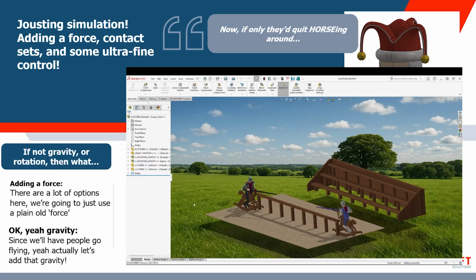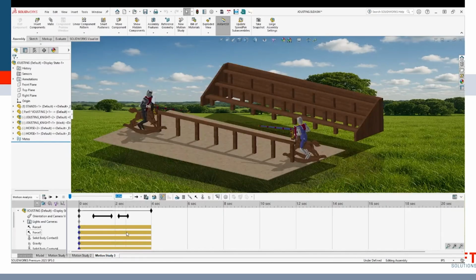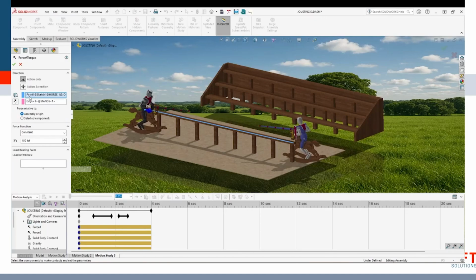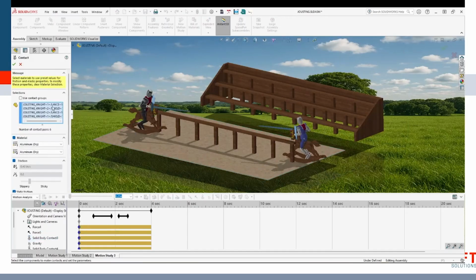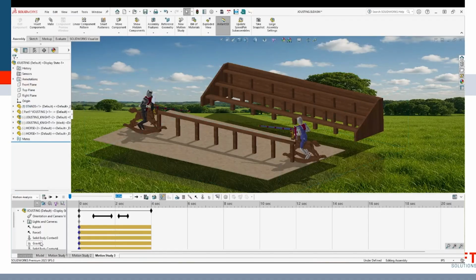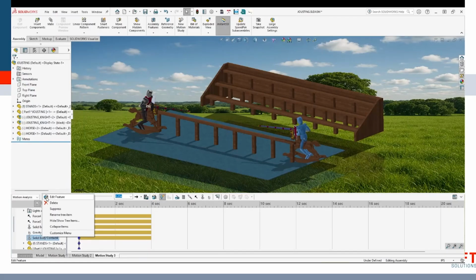And what I did is in here, I had this set up already. I didn't want to bore you with it, but there's your force. I'm going to show you pretty much how this works. You pick a reference, you pick a direction, you define a force. It's that simple, and it will move it for you. You can apply different coefficients of friction if you want, and that's going to have a result in the motion analysis level. But if you just want to get some motion in your video, it's the easiest way to go about it. And I played around with the values. 150 foot-pounds seemed pretty good for what we're moving today.